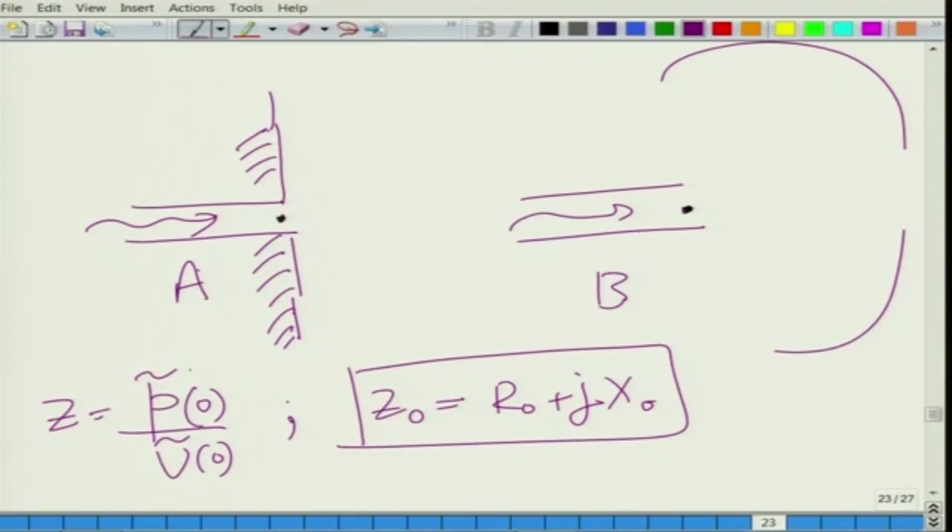It is a complex number as usual, because no termination is anechoic, and no termination is fully rigid. If you consider a simple case, a pipe exposed to the atmosphere, just at the exit of the pipe the surrounding air will pose an impedance. So some waves will be reflected back, and some waves will be transmitted downstream.